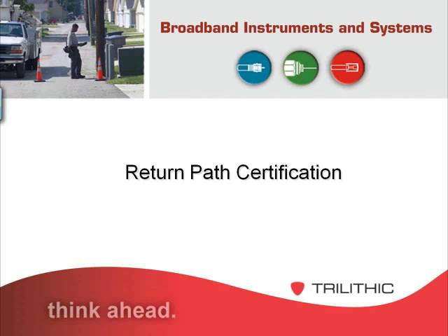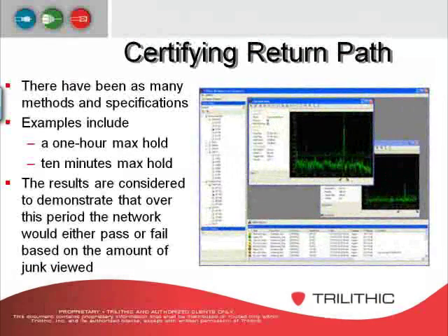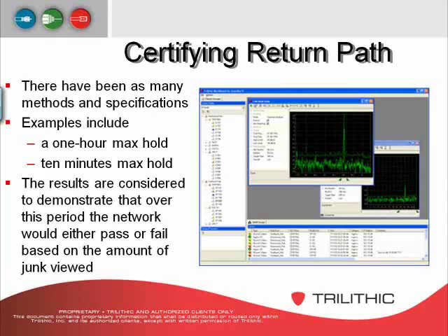Let's first talk about return path certification. There are so many different methods of certifying a return path, or of deciding what's considered certified. Some systems will do a 1 hour max hold on the return trace.